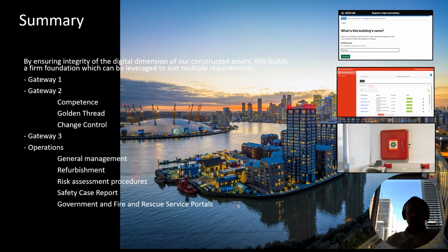Sometimes it has to be manual, but taking the information from Gateway 1, principally the fire statement, through the process prior to Gateway 2 and during Gateway 2, and being revalidated at Gateway 3, provided we've got that information properly stored, properly controlled and hosted and accessible by the right people, it's then important to reuse that information in the management, refurbishment, future assessment and in the safety case report.